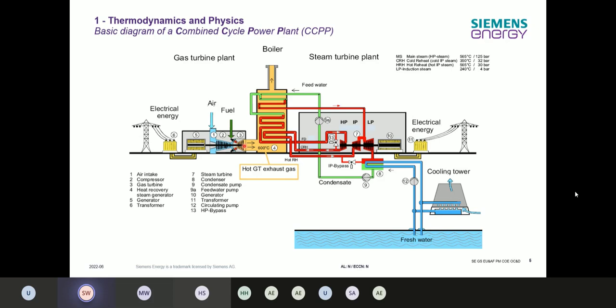Of the power generated in the turbine part, 50% will go into the compressor to run the compressor. So there's a high amount of power used just to run the compressor. But without the compressor, you cannot get the power output, you cannot get the temperatures for the burning, and then it's not working properly. So with the generator, the power goes to a transformer and then into the electrical grid, where the electricity is then going to the households or the industries who need the electrical power.